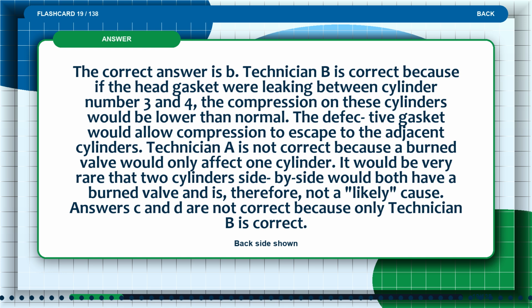Technician A is not correct because a burned valve would only affect one cylinder. It would be very rare that 2 cylinders side by side would both have a burned valve and is, therefore, not a likely cause. Answers C and D are not correct because only Technician B is correct.